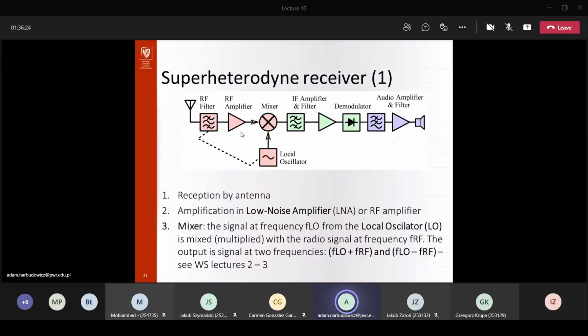Those are typically the two limiting factors: noise limits the minimum power you can distinguish, and nonlinearity limits your maximum power. Everything between is the dynamic range of your device. So with RF amplifiers, you don't want to drive them into nonlinearities, and this can be engineered.